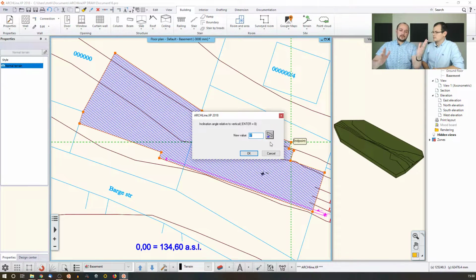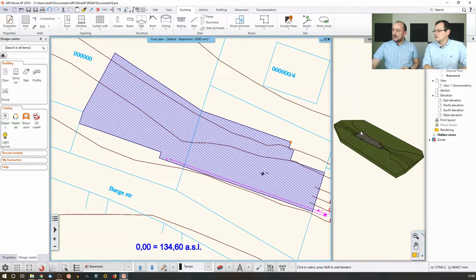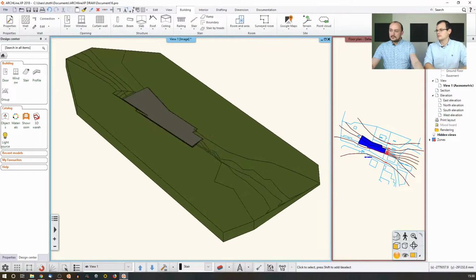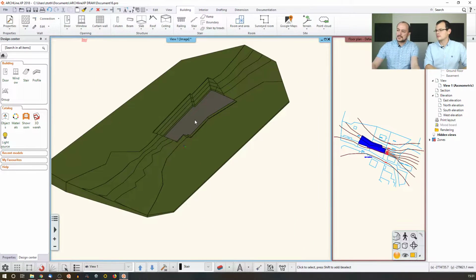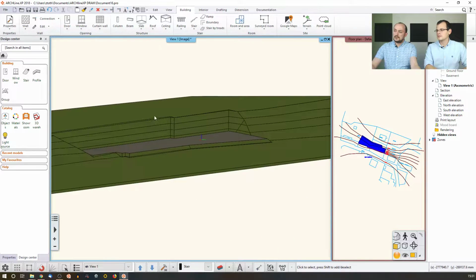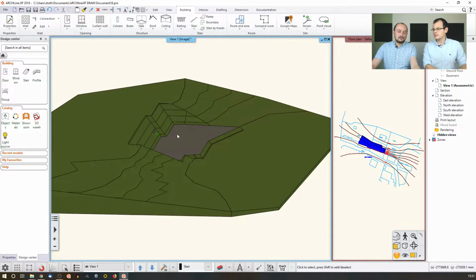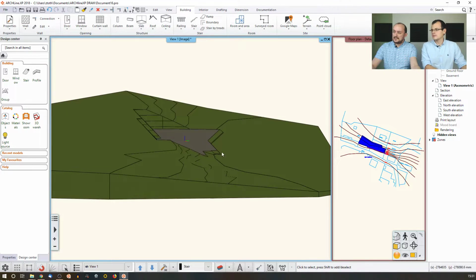So if you would like to decrease the slope, you need to give a larger angle, like for example, I will just add a 45-degree angle. Yes. Then I say OK, and then now I have this option here. So now that's the flat ground, that's the plateau, cut into the ground here, 45-degree angle slope, and extended or added to the ground here when it was necessary. So it's not just sticking out of the terrain like just something. I see, yes. Like a flat plate, but it's already worked together with the terrain, worked into the terrain.